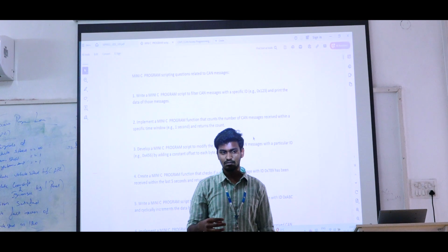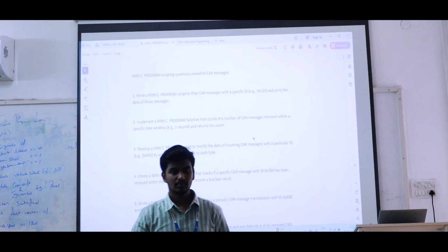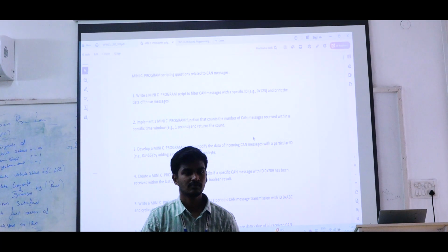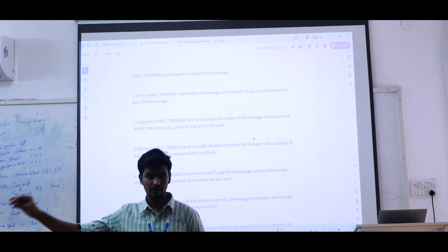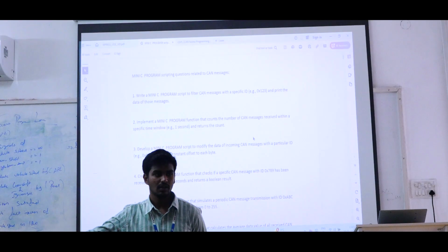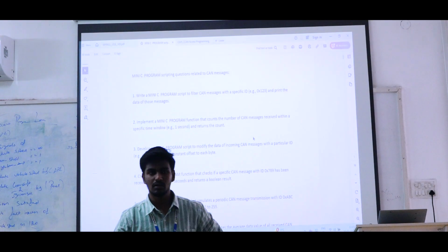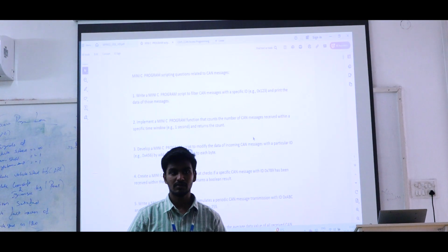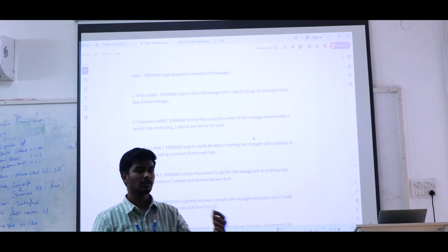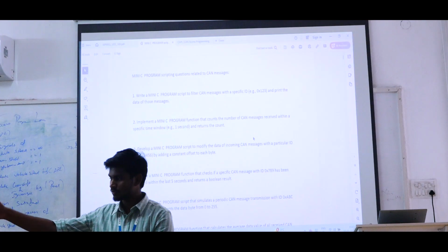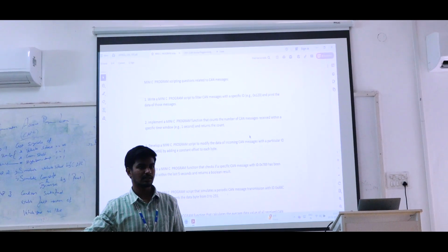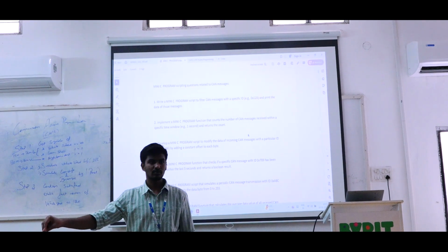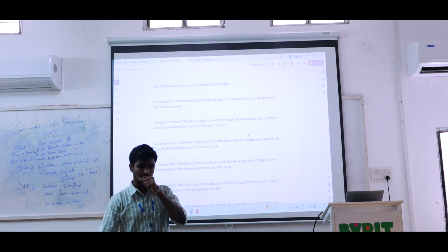Okay, sir. If you give a periodic type of thing, like what you gave in the first day, in such a case we are working with the timings. If we are working with the hardware, then at that time we are only working with on-CAN Rx, which means we are going to receive the values from the tools. At that time the hardware is acting as a real-time car ECU and the PC is acting as a testing tool. So the testing tool is able to receive only.